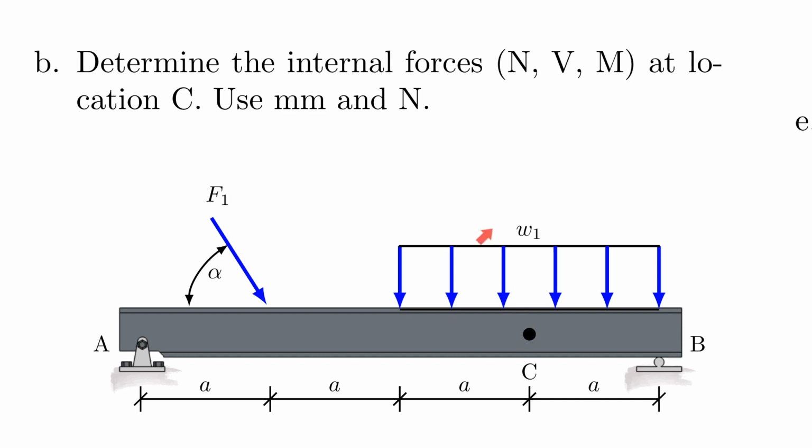However, after you cut the system, either side, you just bring in your internal forces and you calculate them like you calculate cantilever support reactions, just by cutting through the system, even through the distributed force. So don't get too hung up on this. Again, I see that sometimes in the classroom, that initially students get hung up by the fact that the distributed force actually passes over the point, but just blindly cut it off on the other side, no matter if you do the right side or the left side.